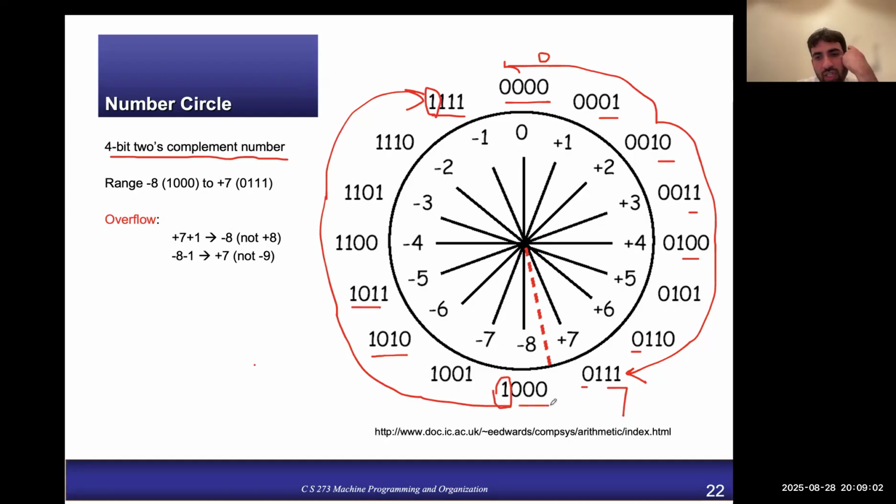So for example, if I convert this one, I don't care about the initial weights because all three bit values are zeros. The weights are 1, 2, 4, 8, so minus 8. Why minus 8? Because the most significant bit is 1, so its weight becomes negative. And here it will be minus 8 plus 1, which equals minus 7, right?